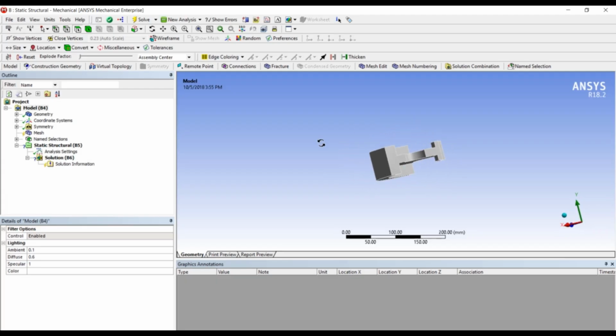The only thing you need to do is, when you take up the model, you should think: is there any axis about which I can have this symmetry? Once you find that, you take the Symmetry option, and then you can cut this body. In reducing the body, the main rule is that the Z axis should be lying in the plane perpendicular to the symmetry plane.